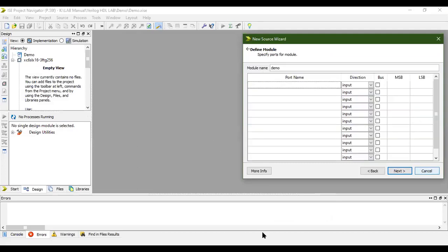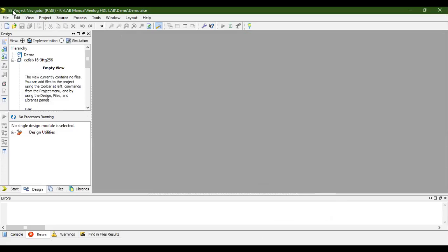So now, which software are we going to use? It's Xilinx ISE. That is the software. The version we are using is 14.5. So I insist everyone install this software while studying. You can execute programs in this, and it will be easier. At the same time, you can even do it online. That is also possible, but I will explain that later.